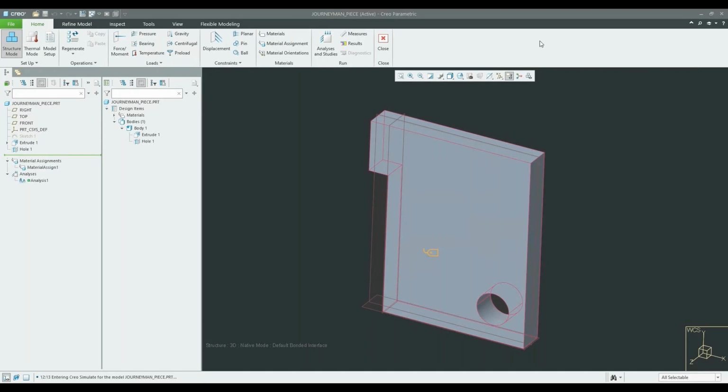One thing that I would say when you're creating a new material is where it says description, add a note. Tell me or whoever's looking at this where you're getting these numbers. Because if we run an analysis and it doesn't come back right and we have to troubleshoot it, one of the things we'll have to check is your material properties. Are they accurate?